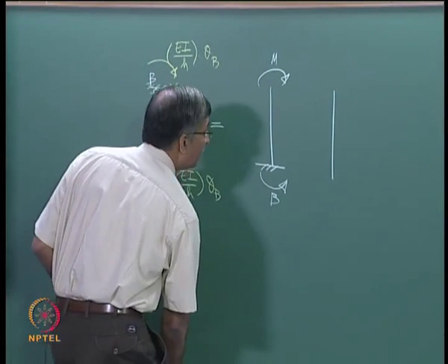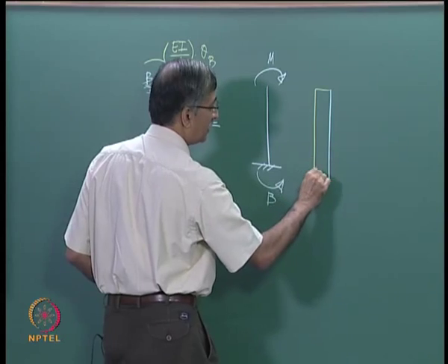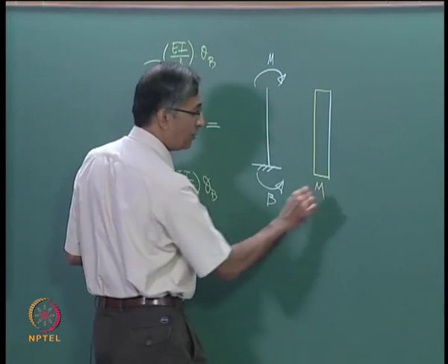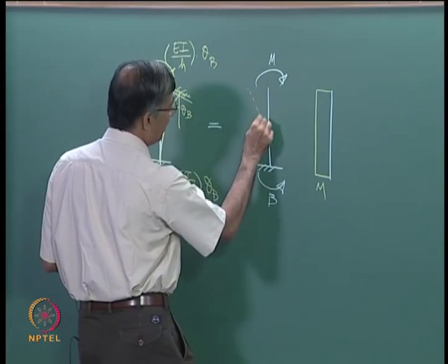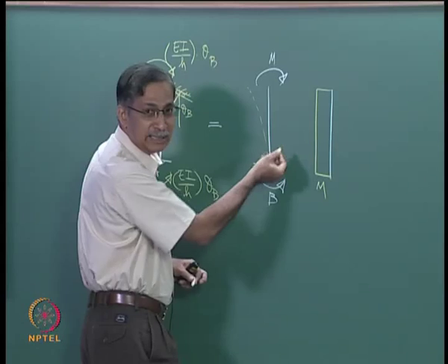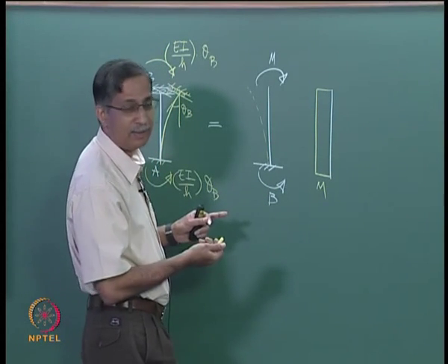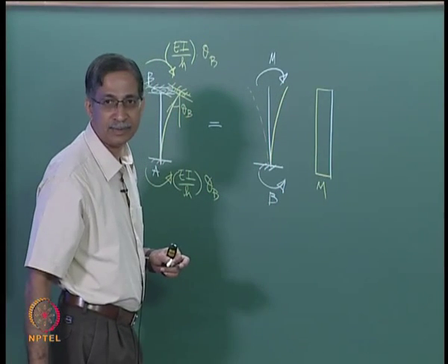Okay, so the tension is on this side, right? Tension is on that side. Is it clear? And the bending moment diagram will have a constant moment here. So if it were to move this way, you are going to have tension on this side, so it does not work. So that is one clue that it has to rotate like this. Is it clear?